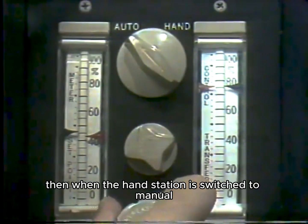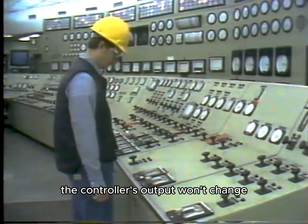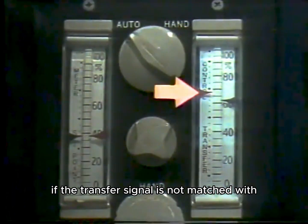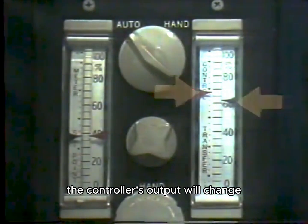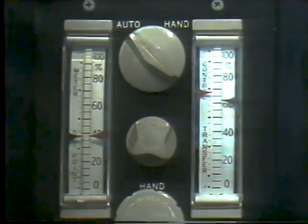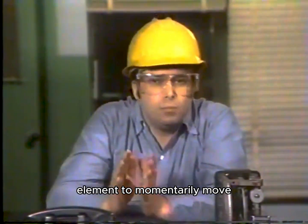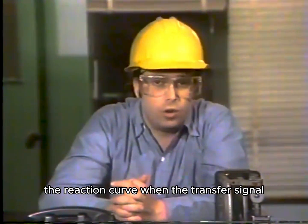Then, when the hand station is switched to manual, the controller's output won't change. If the transfer signal is not matched with the controller's output before the switch, the controller's output will change when the selector is switched. The change will cause the final control element to momentarily move. This will appear as an undesired bump in the reaction curve.